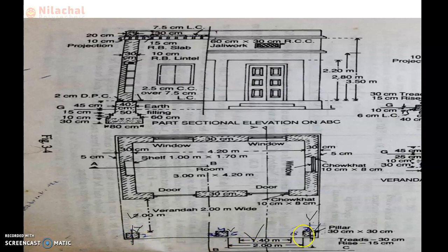Same another side also half of the pillar is considered, and in between one pillar is provided here. So in both sides half of total is 1 number, and here also 1 number. Total 2 numbers of pillar are between the front wall of veranda. So we need to deduct the 2 numbers of pillar value in case of veranda.